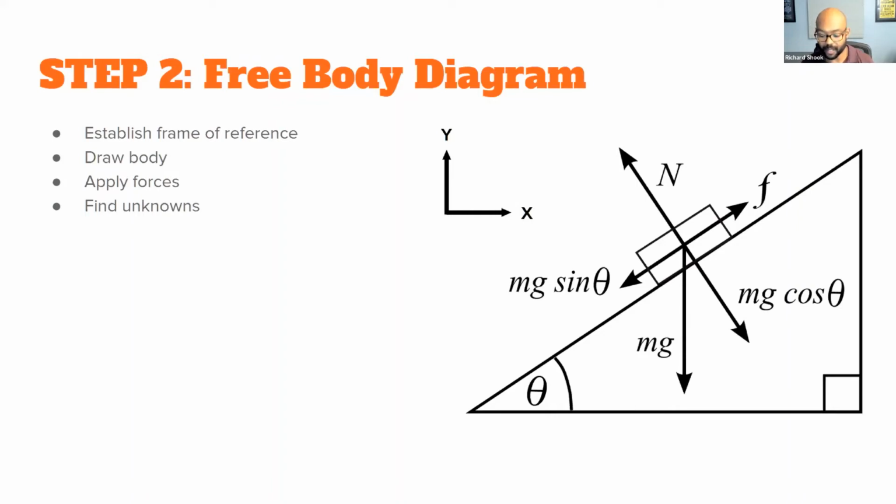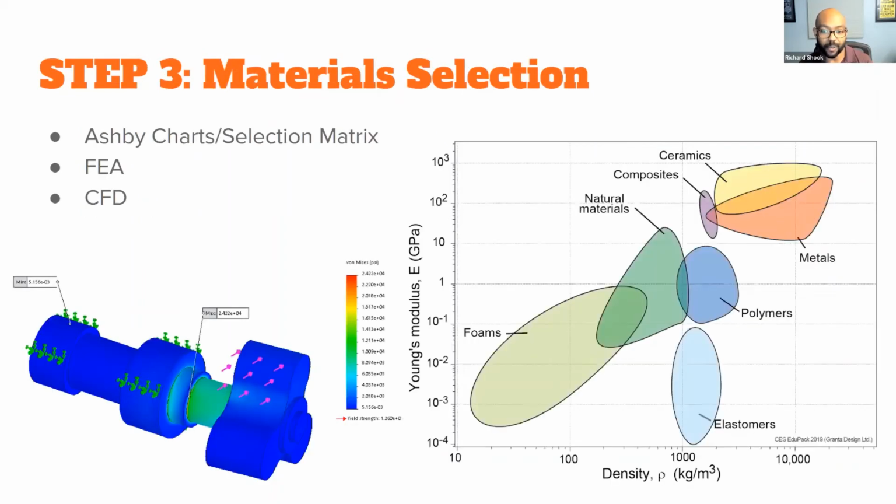And that kind of ties into selecting the material, because with the 3D printing process and with all the other different manufacturing processes, you do have some limitations as far as what materials are available and the strengths. When we start to look at the material selection portion of it all, what we typically use in engineering is what's called the Ashby charts.